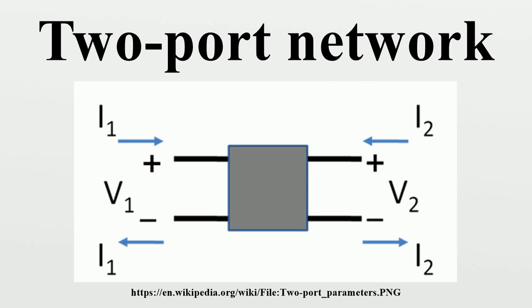Hybrid parameters, where this circuit is often selected when a current amplifier is wanted at the output. The resistors shown in the diagram can be general impedances instead. Notice that off-diagonal H parameters are dimensionless, while diagonal members have dimensions the reciprocal of one another.